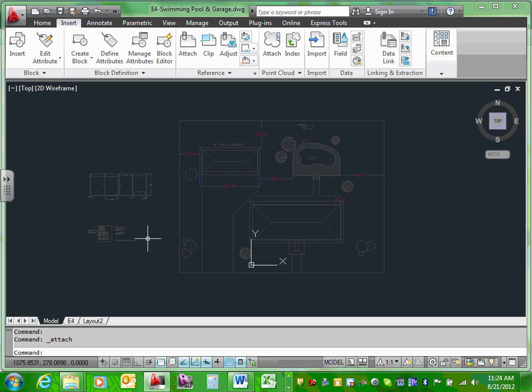The other thing I did, Jeff, is I came over here. Remember how we edit the layers? Click on that one. These are all the layers that you have. The one that we just brought in, this is old. Both of them need to be grayed. So what I do is grab the first, hold, yep, you got it, and type color 8 here, so you're good.